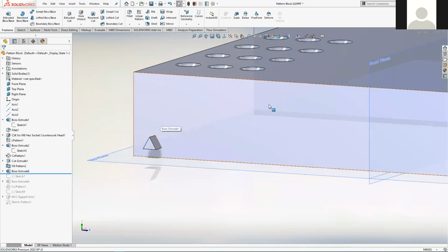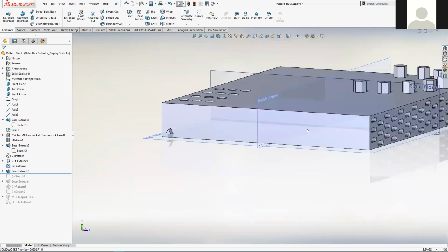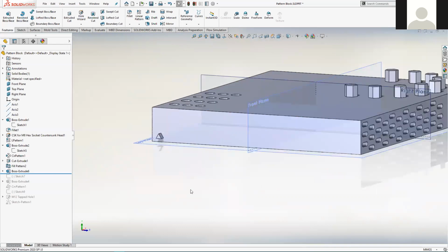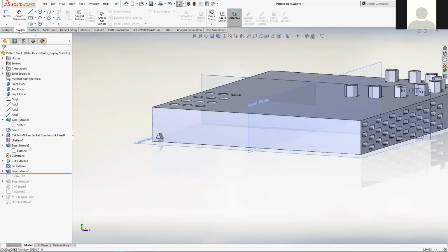Now what I'm going to do, I'm going to create just a sketch which isn't going to be part of another feature at this point. It's just a sketch on its own, which I don't think that we've done yet. So if you just want to initiate the creation of a sketch and you don't want to instantly use it to create a feature, the way that you would do that is select the sketching tab and then just click on sketch on the far left hand side there.